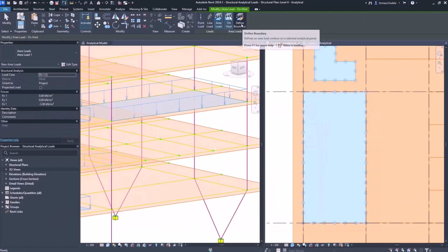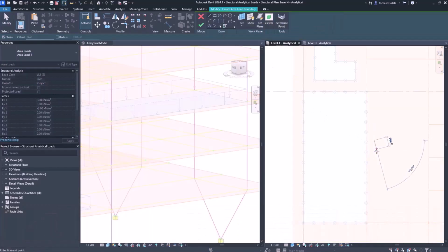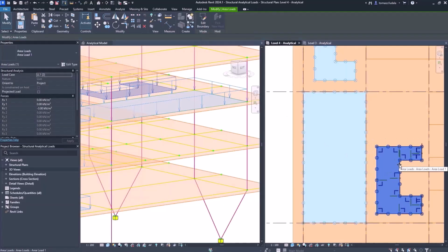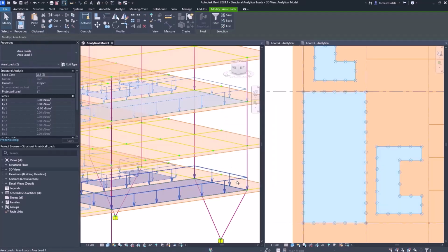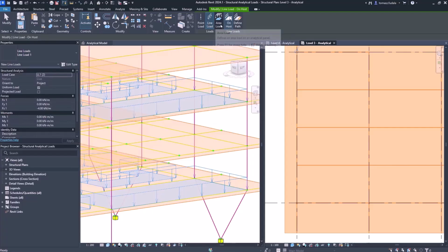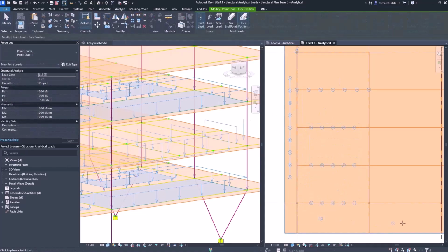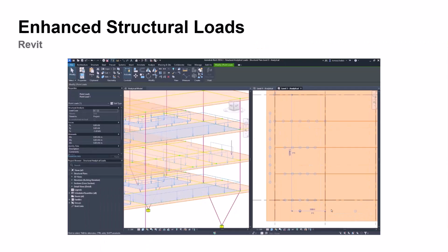And of course, depending on the load duration and type, different natures of loads can be created. So various types of loads such as point, linear, and planar loads can be applied to a structure, assigned to previously defined load cases. These loads can be easily and accurately applied to specific areas of panels and members, or copied to another analytical host, for instance.